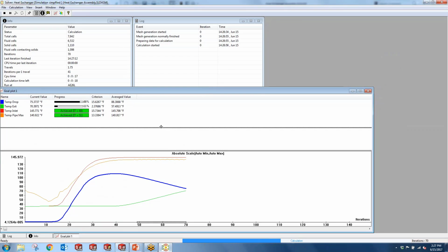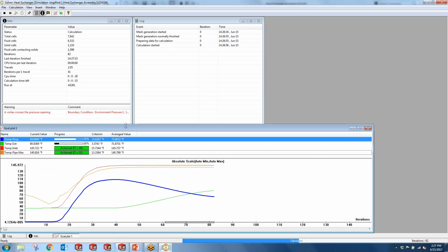And here we see the goals. They're color coded, and we're just seeing the value of them. Because they're all the same parameter, it's going to show us the actual numbers of what each one's temperature is. If it was different parameters, so maybe you have one that's speed and one that's temperature, it's going to just show you 0 through 1 level of refinement. So what the solver is trying to do is find a case where within this bounding region, the actual numbers have converged to a flat line. So we know that that is a converged state of the simulation.